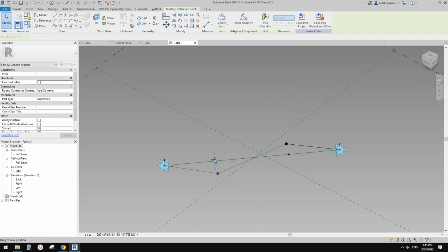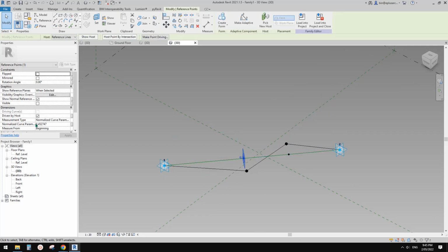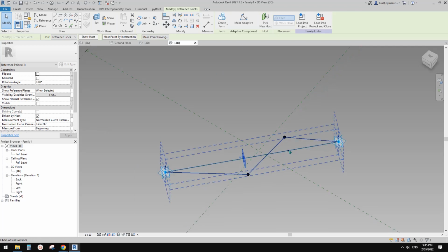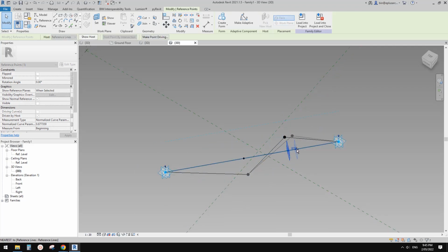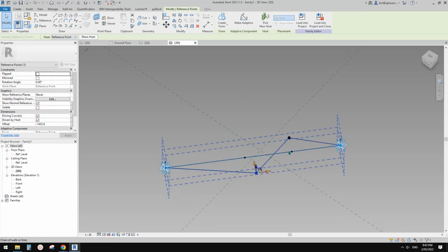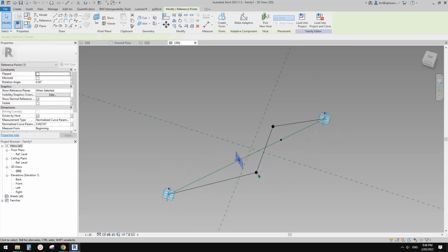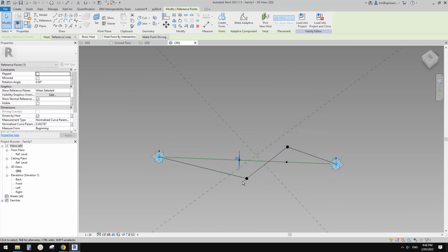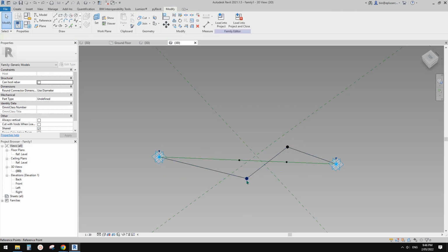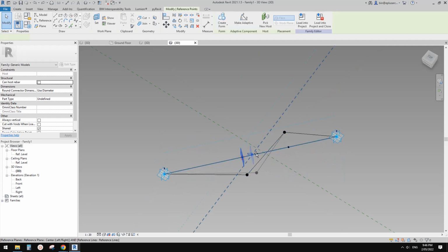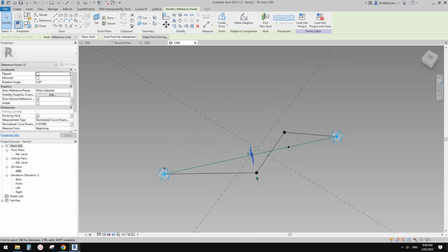And also you can, if you want to, normalize the curve parameter. So you can even set a parameter to it. So you can adjust them after you load this into that mass. But I'm just going to leave it for now. And also this, oh hang on, did I just click Control Z? I think, yeah, oh good. So make sure you only move this point, not directly move them.